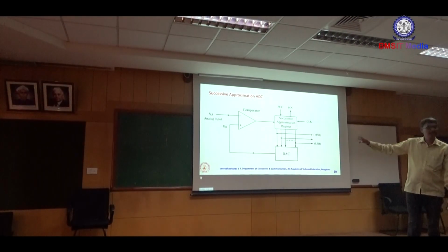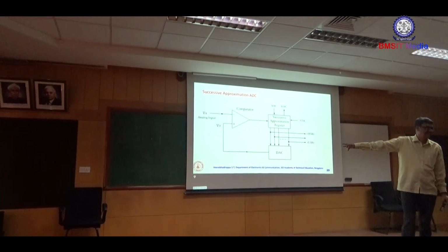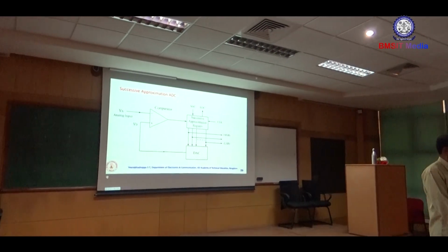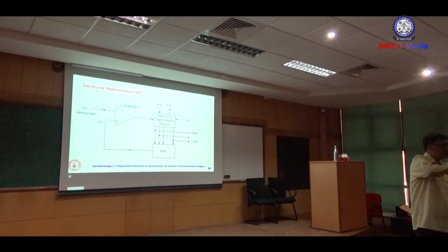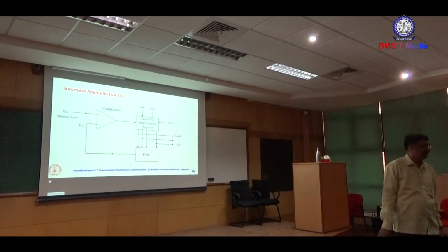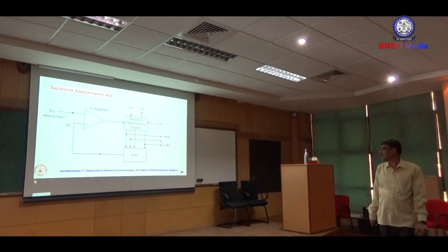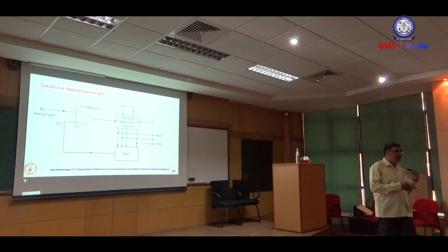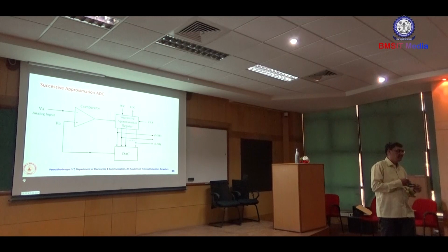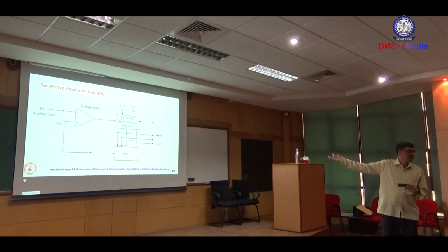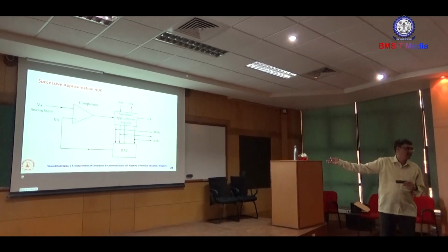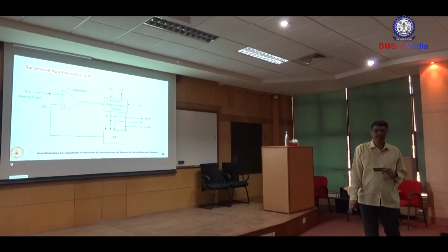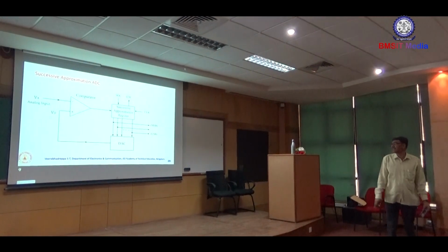In the examination, it is also explained with one simple example, either 4-bit or 8-bit. With 8-bit you need to calculate many things, but in a 4-bit you have to verify each step and then take it. This is successive approximation, so how many clocks are required? Until all the bits are verified, it verifies over all the clock periods: n clock pulses plus 2 clock pulses, here 4 plus 2. So next, this is about successive approximation.